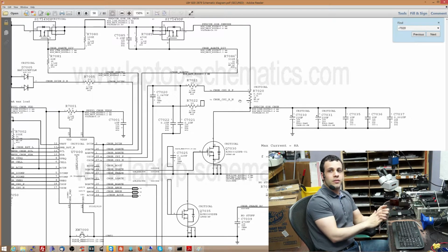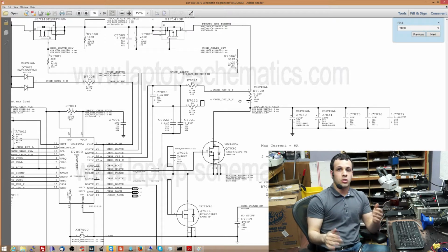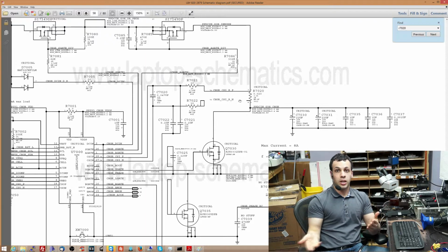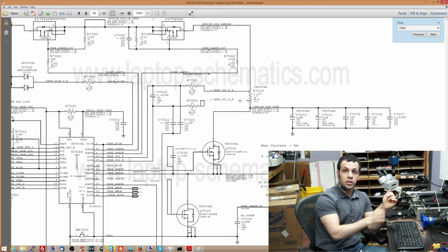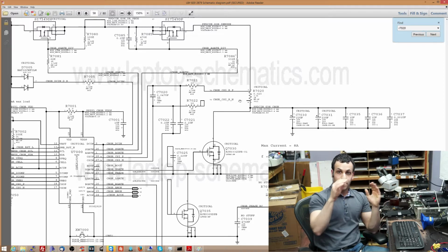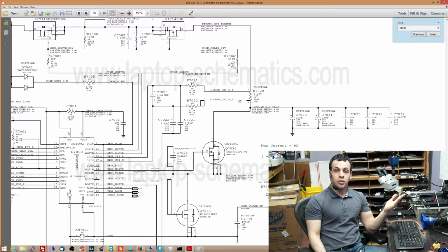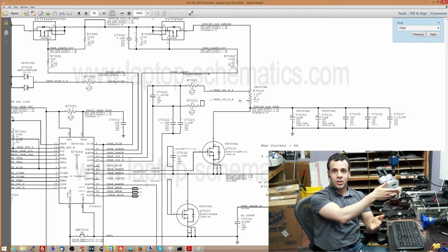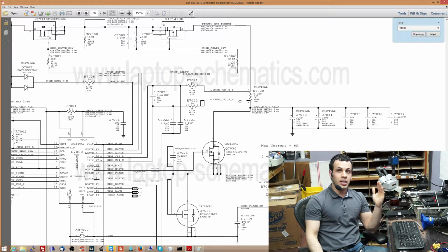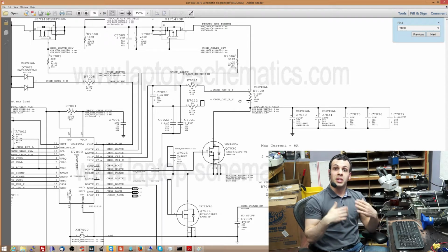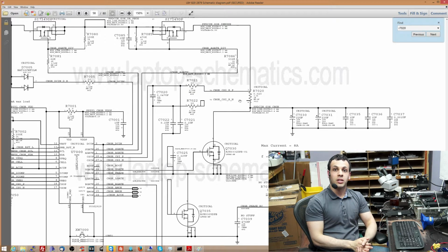When you see 75 millivolt voltage difference, we're using 2 amps. When you see 100 millivolt voltage difference across that resistor, we're using 3 amps. If you program it with that information, all you have to do is tell that chip that for these predefined values of voltage difference, here's how much amperage the chip is using. You can pretty much tell how much amperage the system is using based on those voltage differences. And that is one of the tricky ways that we figure out how much amperage the system is using so that we can tell you, here's how much time you have left to use your laptop.